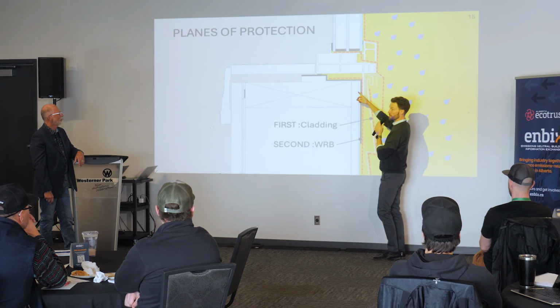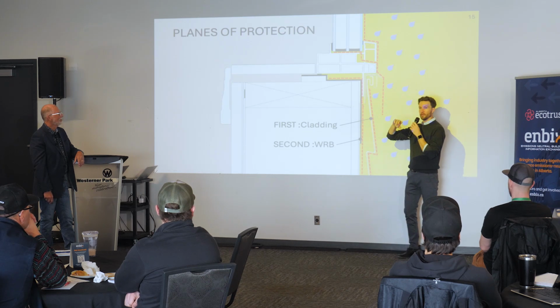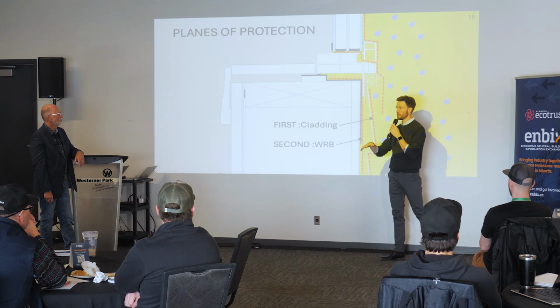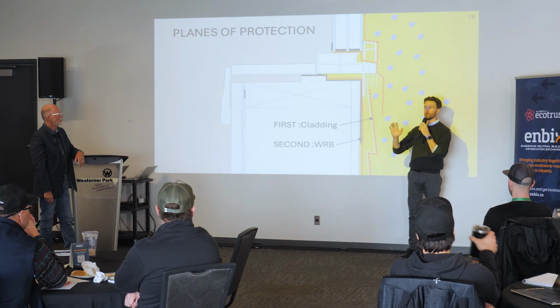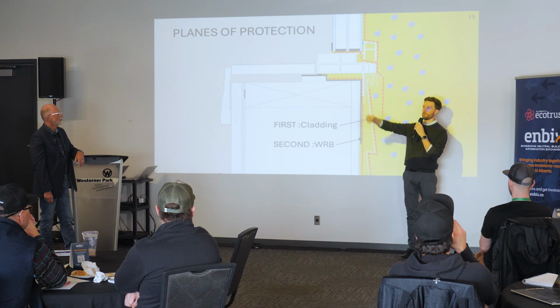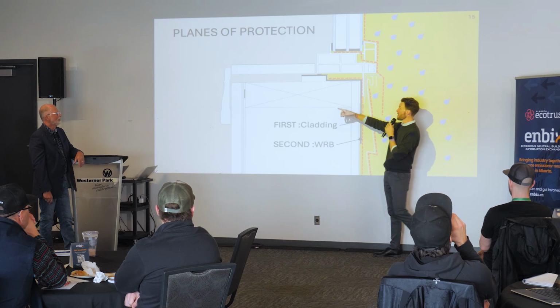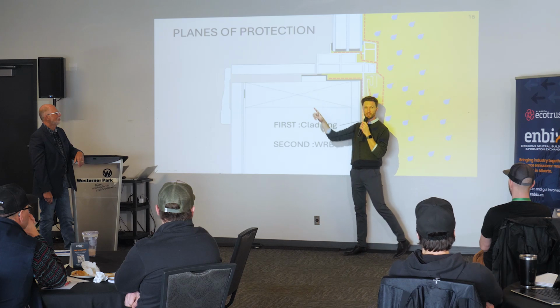The other thing is with the insulation question, I love this. In Ontario, at least, I wonder what practices are here, but in Ontario, standard practice is install the windows, can of spray foam, four sides. We don't see back dams and we don't see sloped sills.